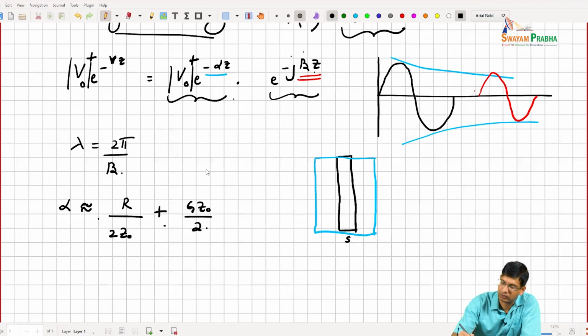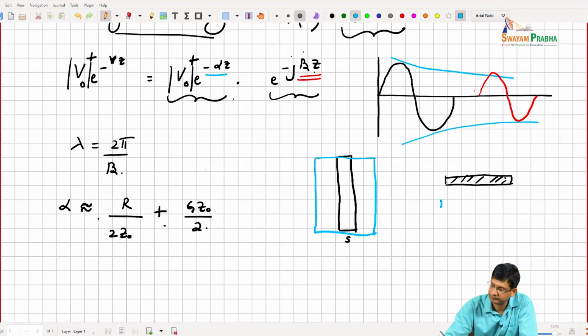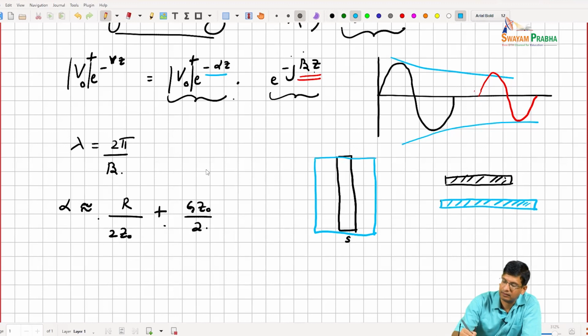And if we were to look at the side view, we are looking at a signal layer, and then underneath it, we have our ground layer. And we are basically defining unit inductances, unit resistances, and then loss, and then capacitance. That's what this looks like for each section of this line.